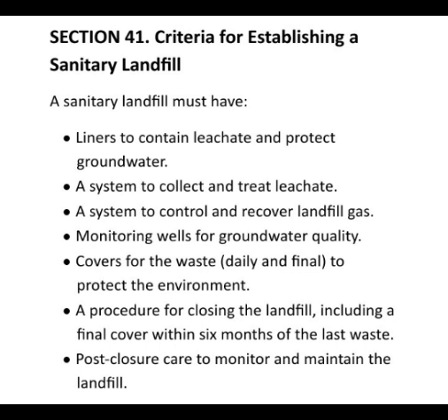A sanitary landfill must have: first, liners to contain leachate and protect groundwater. So what is leachate? Leachate is the harmful liquid formed when water passes through waste in a landfill. It contains chemicals, bacteria, and other pollutants, so it must be collected and treated properly to prevent contamination of soil and groundwater. Next, a system to collect and treat leachate, a system to control and recover landfill gas, monitoring wells